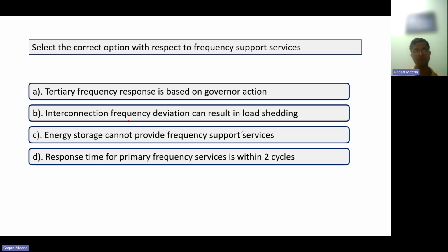Energy storage can provide frequency support services, so that option is not correct. And response time for primary is in seconds. For inertial response, it is within cycles.